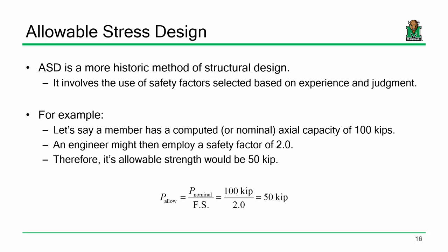So what I've done is I've introduced a factor of safety. Now, if this table actually fails at its nominal capacity of 800 pounds, but its allowable capacity is 400 pounds, what's the factor of safety there? 2, right? So I've incorporated a factor of safety of 2. Now, that is a reasonable method of design for engineering judgment.